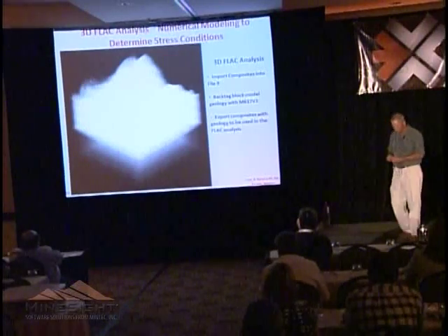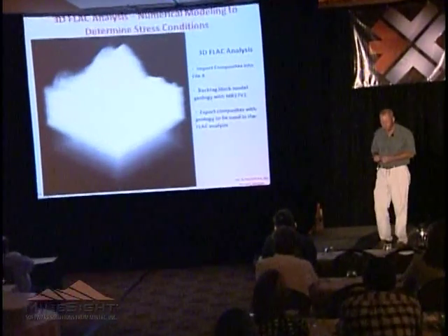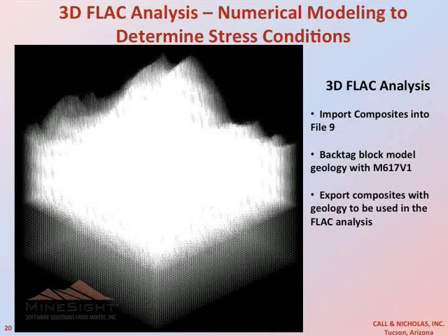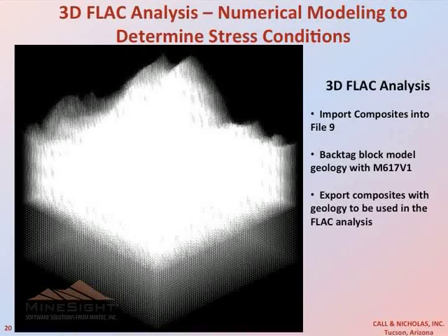3D FLAC modeling is a numerical analysis or numerical modeling technique that we use a lot to determine the stress in rock. Unlike a regularized block model, the 3D FLAC model, although it has centroids, the elements that are used in there are not regularized. They're not like a block. They can be any shape or any size that the modeler determines.